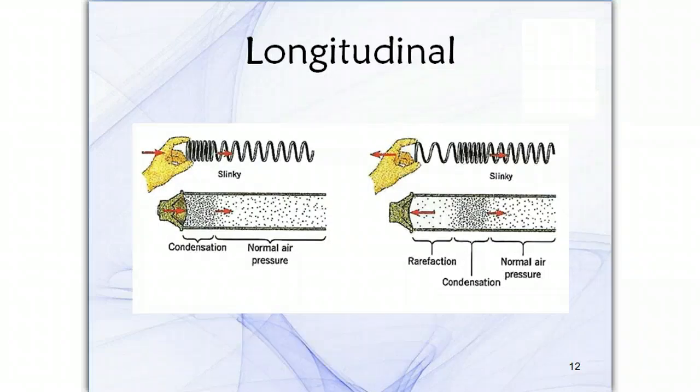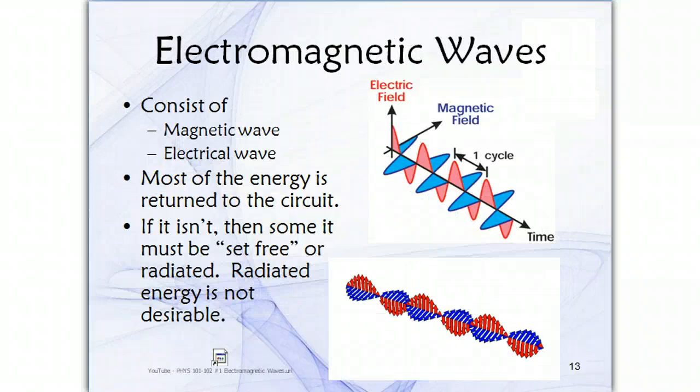And then there are radio waves, radio frequencies, the RF spectrum: a frequency or rate of oscillation within the range of about 3 hertz to 300 gigahertz. The currents that oscillate at RF have special properties that are not shared by direct current signals: the ease with which they can ionize the air to create a conductive path through the air, and the ability to appear to flow through an insulating material, a dielectric insulator or in a capacitor, say.